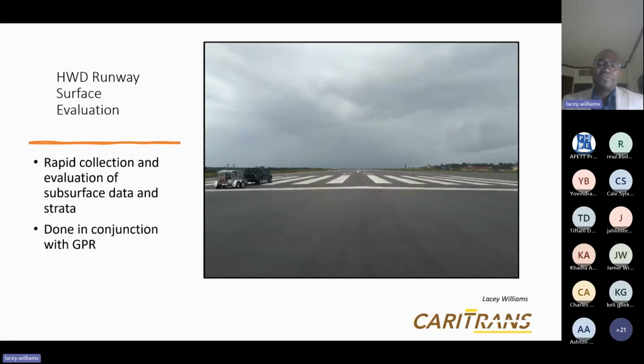And I'd also just like to close by saying that the key to it, whether you're using the FWD, a ground penetrating radar, or the laser profilometer, is that you must be regularly collecting your data. And don't think that because your infrastructure is fairly brand new, you can simply walk away and wait until such time as you see the deterioration. At that stage, the old adage goes, a stitch in time saves nine, and it's no different with the testing equipment that we have.